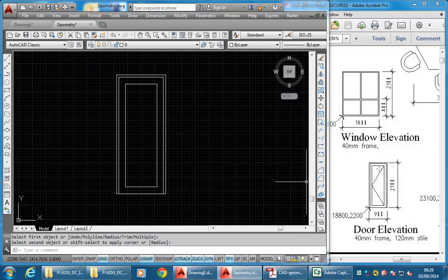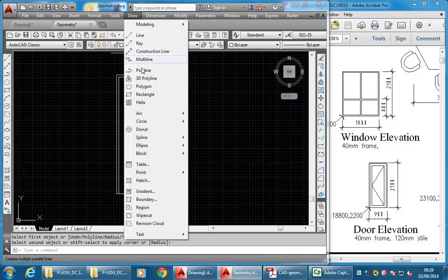And the way the chevron, that arrow there, if you don't know, is called a chevron, and that shows the direction that the door opens. The way that's drawn, I think, is actually a little bit incorrect. It should be drawn over the door itself, not just the glass.